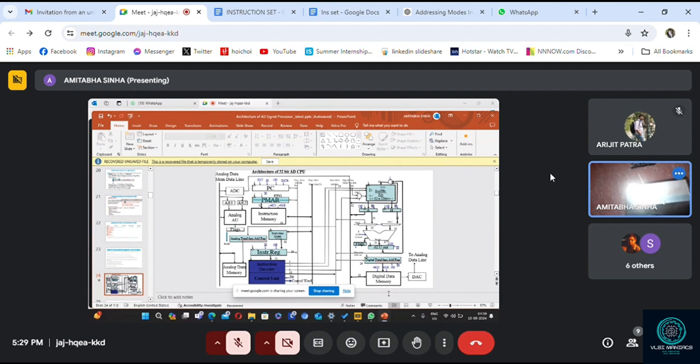We agreed? Yes, sir. Now instead of resistance, you use a diode. Now what property does a diode have? The diode has current and voltage, and that relation is nonlinear. And if you go through it, it is logarithmic. It follows ln, isn't it, the current and voltage? So if we use a diode, automatically the output will be proportional to the logarithm of the input.